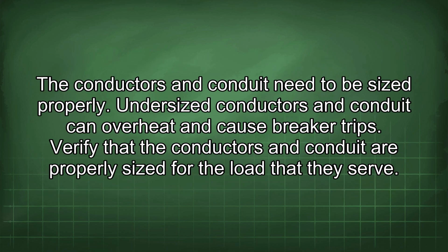The conductors and conduit need to be sized properly. Undersized conductors and conduit can overheat and cause breaker trips. Verify that the conductors and conduit are properly sized for the load that they serve.